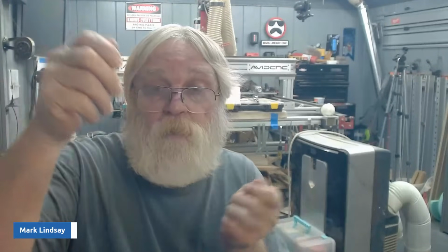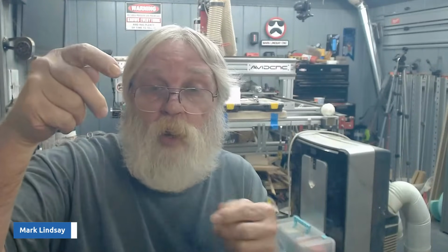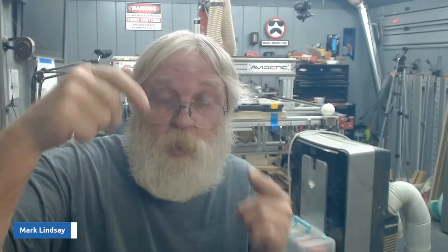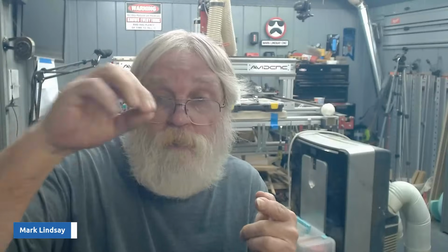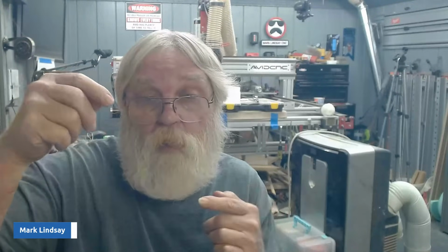You can unplug a cable at both ends, put the positive at one end and negative on the other, set your multimeter to check for ohms of resistance, and do a continuity check. That lets you know if it's open, that means that you've got a break in there somewhere, or your connection is wrong or something like that.